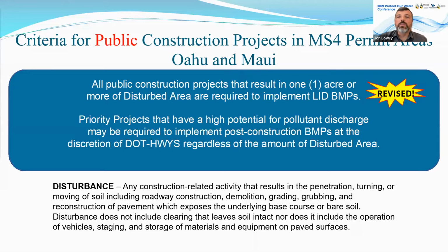And then furthermore, if it's a priority project, something like maybe a refueling station or a parking lot, even if they are under an acre of disturbance, at DOT's discretion, they could require post-construction BMPs. And it's important, real quick, since we are talking about post-construction versus construction. I know in construction BMPs, the definition of disturbance can include areas where you're just staging equipment. Maybe it's a paved parking lot, but the fact that you're using it as a staging area has to count into your disturbance. For these post-construction BMPs, that's not the case.